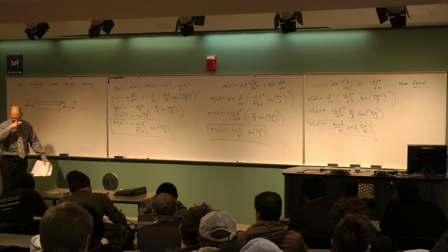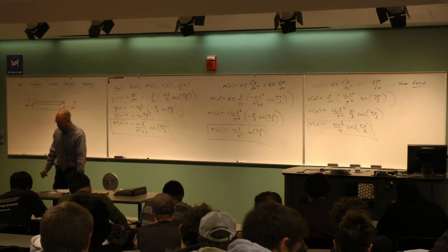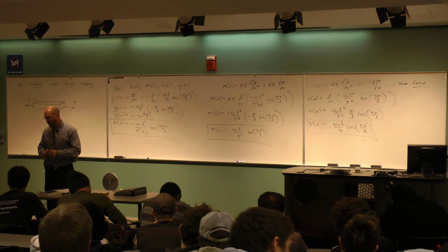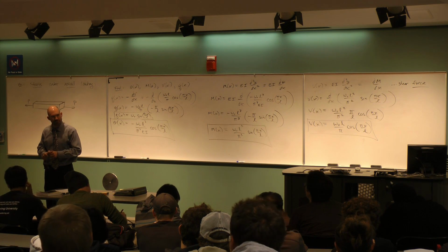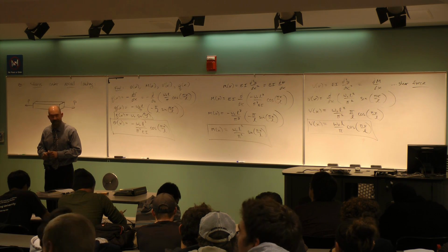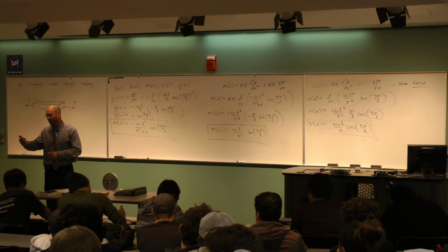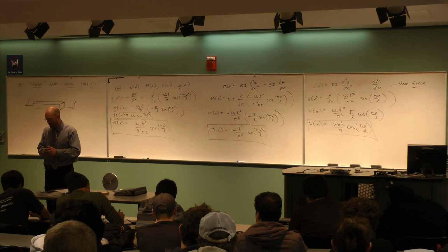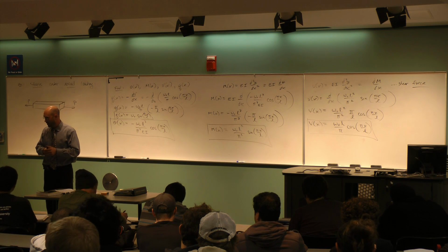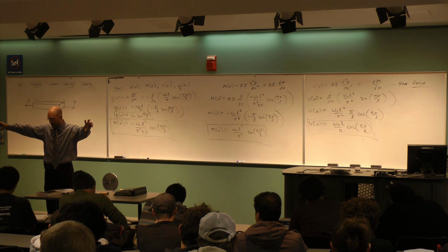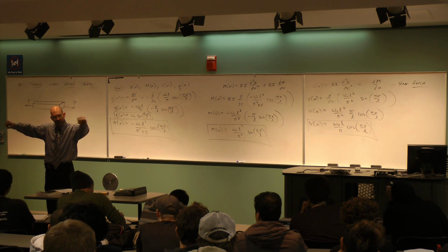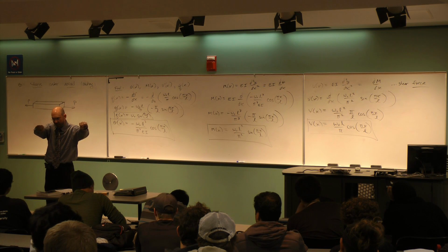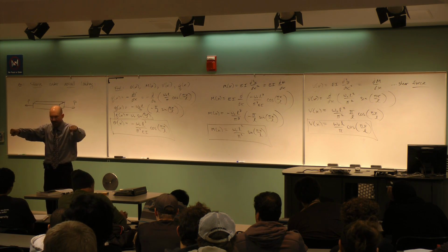Okay, and so let me ask you first a question. If I pull on a bar that's made of steel, how much load does it take to break it? Can you give me a number? We don't know. What don't you know? How thick it is. Okay, well, so, right, how thick it is, what's the failure property. Okay, besides the thickness, what else probably matters? Does the length, how long it is, matter, do you think? If I'm just pulling on it, the bar is half as long, and I knew a certain load would break it. If I take the bar half as long and put the same load, can I still break it? Probably. So probably not the length, but somebody said thickness.